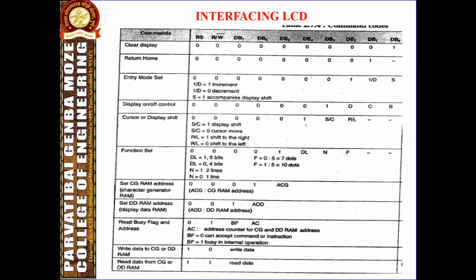The CGRAM stores the characters in the internally generated character code. Before sending the command or the data, it is essential to check the busy flag. The flag will indicate whether the LCD is busy or ready.